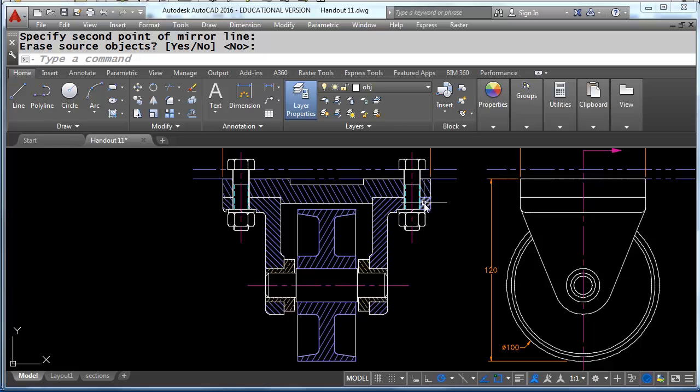If you see the same pattern all in one area, that indicates that this is one part. But as you know, we have two axle supports. So although I'm using the same pattern with the same scale, the hatch pattern for this axle support, I've reversed the angle to make them look like they're mirror copies of each other.